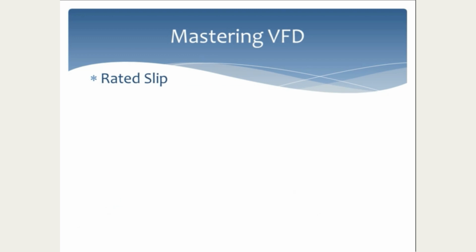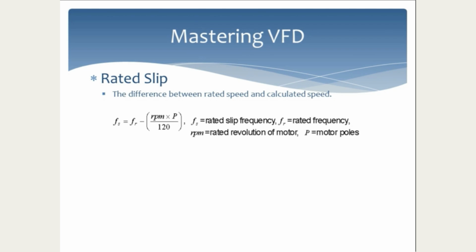We are familiar with parameters like voltage, power, current and speed. But rated slip, what is the concept of rated slip? It is the difference between rated speed and calculated or theoretical speed. Here I am sharing the formula to calculate rated slip.